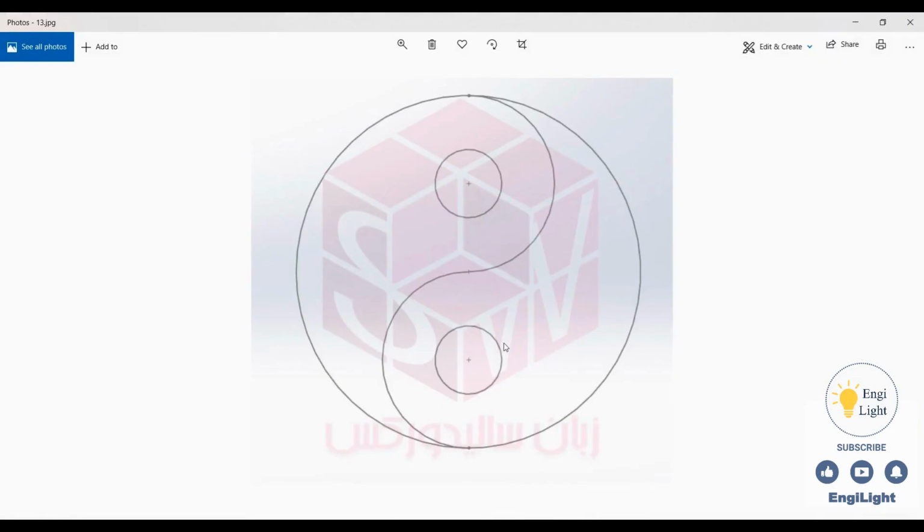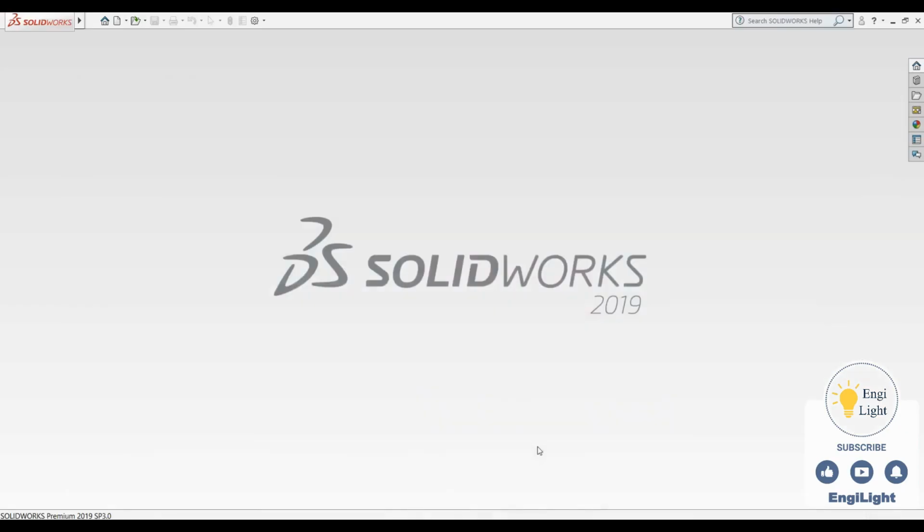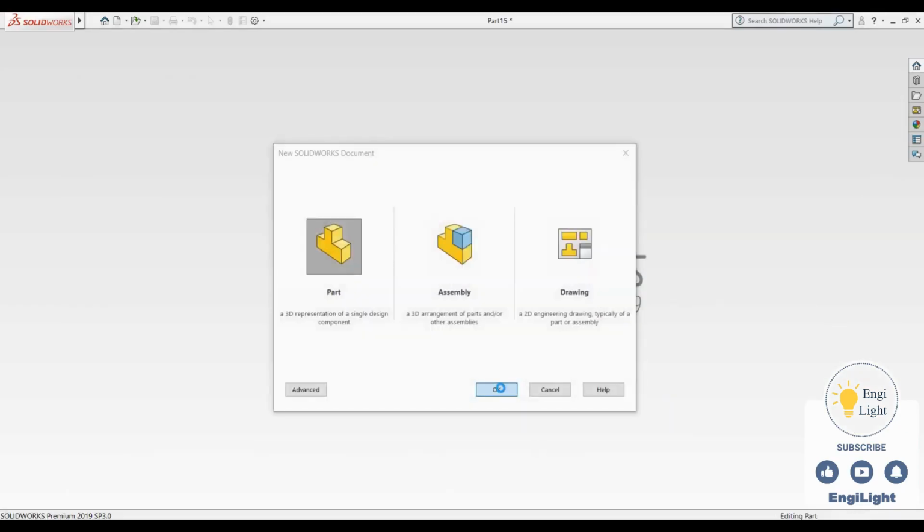This sketch doesn't cover any new tips, so try to complete this exercise using your own ideas. To draw this sketch, I'll first create the large circle, then add two equal circles here and here, tangent to the larger one, and place two more equal circles at their centers. Using these tips, I go ahead and draw the sketch.